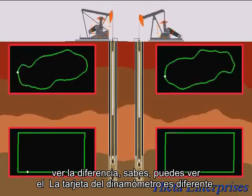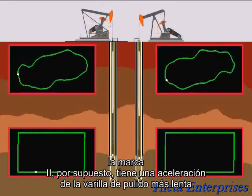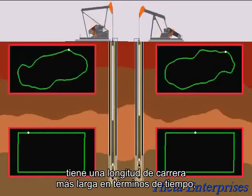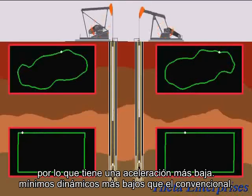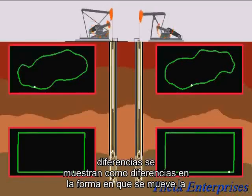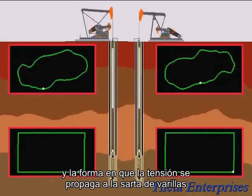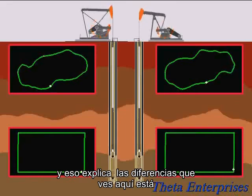You can see the dynamometer card is different. You can see that the polish rod velocity is different. The Mark II, of course, has a longer time-wise stroke length on the upstroke, so it has lower acceleration and lower dynamic loads than the conventional. But then on the downstroke, the Mark II has to go faster than the conventional. Those differences show up as differences in the way the rod string moves and the way the stress propagates through the rod string. That explains the differences that you see here.